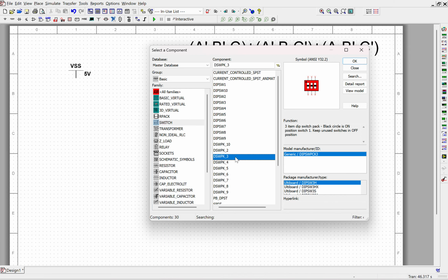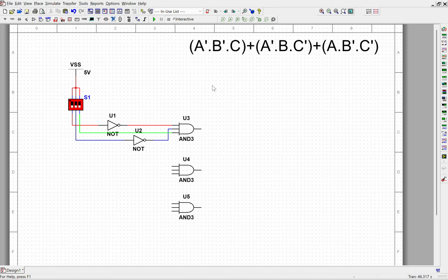And also a little trick to speed things up a little bit, because your second expression uses not A, you don't necessarily have to have its own separate NOT gate. You can steal it from this one up here. So that will still be not A because it's fed from your A switch, and you can feed it into there. So that's not A for this one. B we'll just take from B there. You can't go after the NOT because otherwise you'll get the incorrect signal.